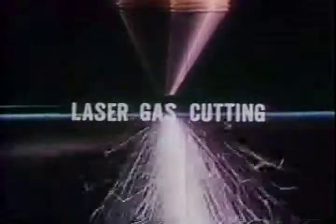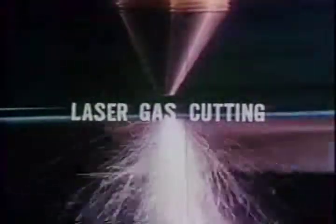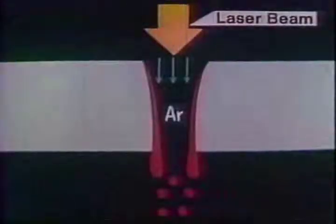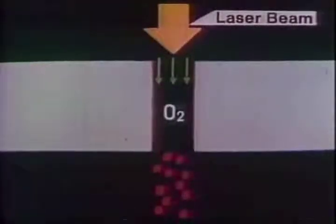Laser gas cutting. Laser gas cutting is also one of the important fields of application of the high energy density beam. When the deep penetrated weld pool is blown out by a strong gas jet, for example an argon jet, the process changes to cutting. The use of an oxygen jet on oxidizable materials is very effective to increase both the cutting speed and quality.